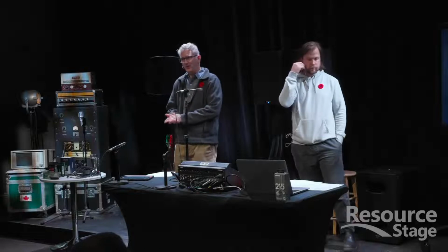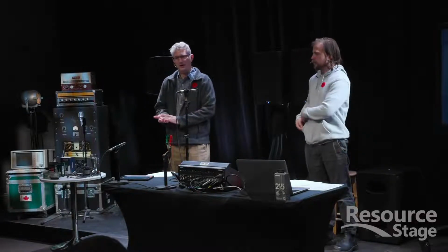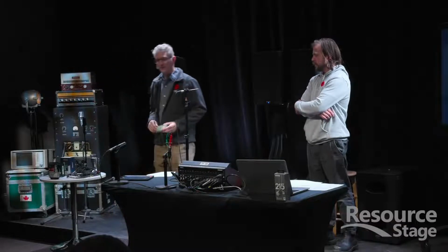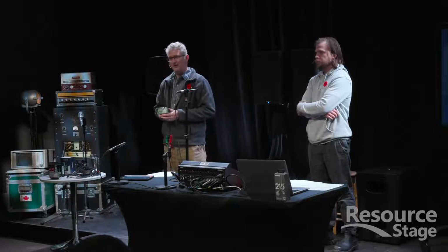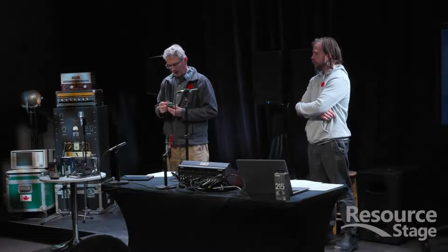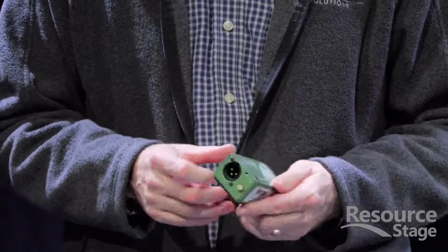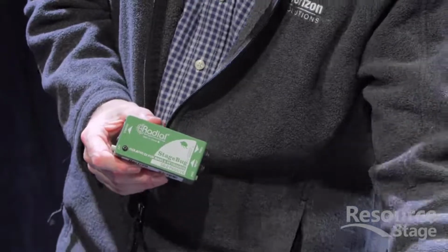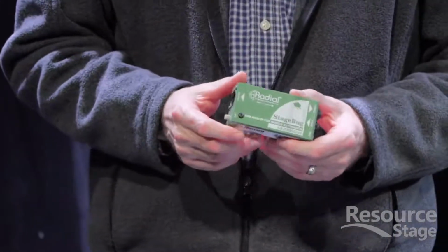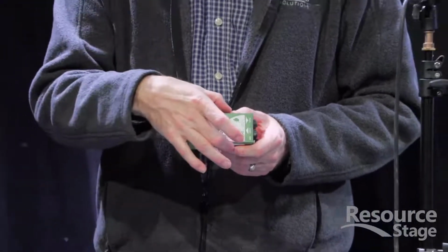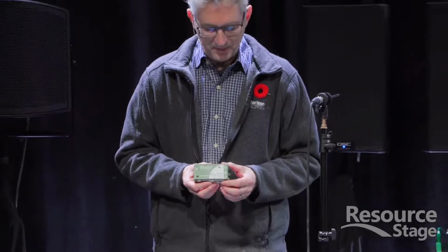Yes. So if you wanted to plug in a keyboard or a guitar, the best thing to do is to use a device called a direct box. We've got a number of them here. This is a Radial SB2 stage box. We've got 1/4-inch inputs on one side and an XLR on the other. This direct box, they are designed to convert the signal from high impedance input to a low impedance output. There's a transformer built in here, at least in passive ones, there's a transformer built in here. And so it does that. It also converts it from an unbalanced signal to the balanced signal so that we can run a long distance.